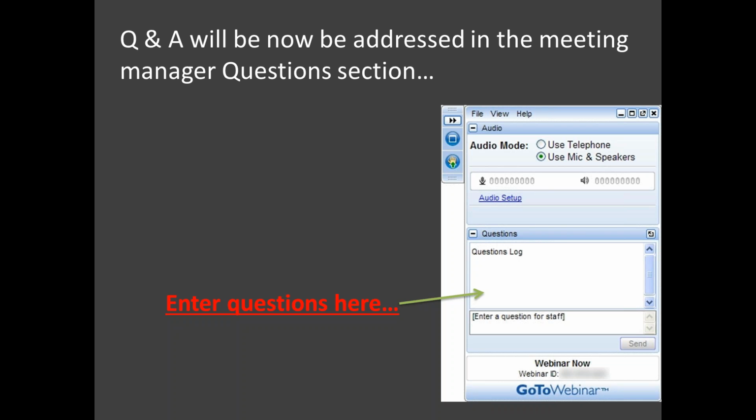I'm talking parameters, not iProperties. That parameter will be shrink. So if you're pouring an iron casting or a brass casting, it has a certain shrink rate. Every dimension they put into their design will be linked to that shrink rate times whatever the dimension is supposed to be. So if their shrink rate is 1/10 of an inch per foot, then it's going to be 1.08333 blah, blah, blah, times whatever value their casting is supposed to be long.